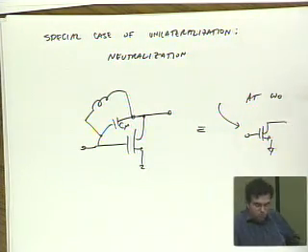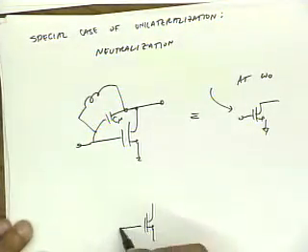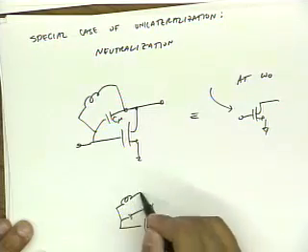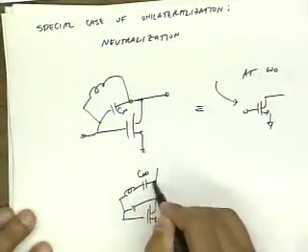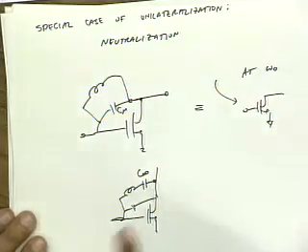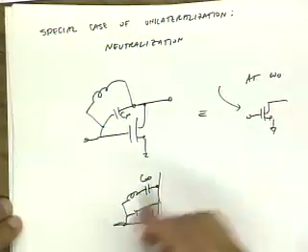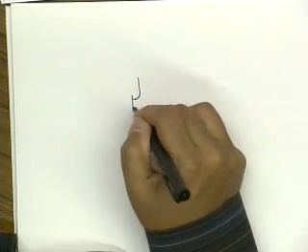With biasing? Sure, I mean, this is an AC schematic, so the way you would do it in reality is you'd use a big capacitor here. Okay? So if I unilateralize my device, or in this case neutralize, which is easier to say than unilateralize, if I neutralize my device, then I actually do end up getting more gain out of it. This is one way of neutralizing a device, but there's a really cool way of doing it if you have differential circuits. So here's another way of looking at neutralization.